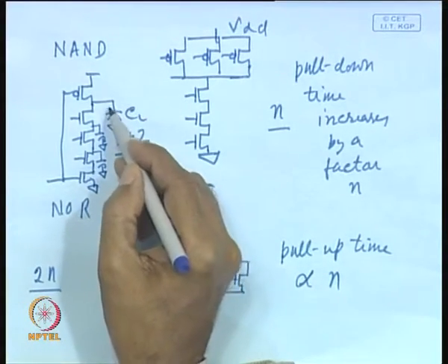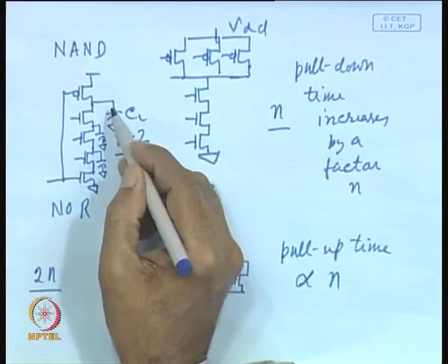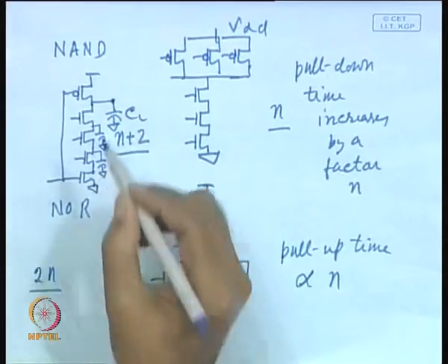here will be distributed in these 3 capacitors, that will lead to reduction in the voltage. As a consequence, that voltage cannot be precisely defined. You cannot tell it high, you may not tell it 0. It all depends on the relative value of the various capacitances and the way the charge sharing occurs.